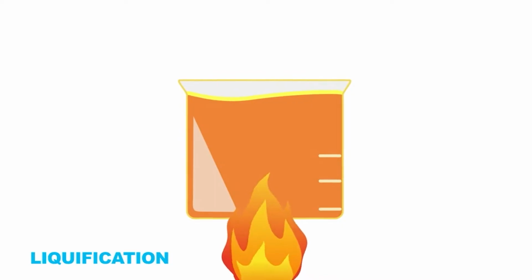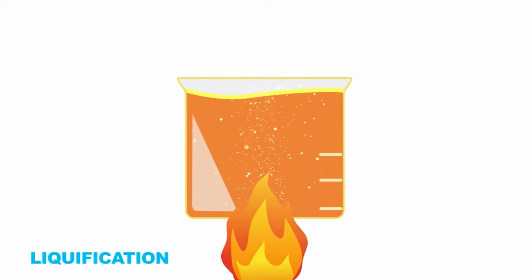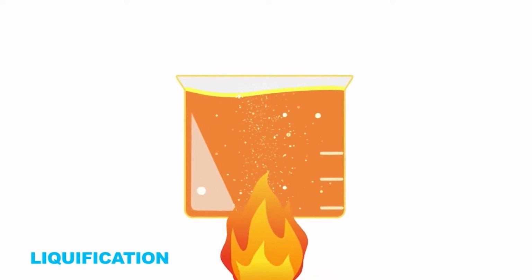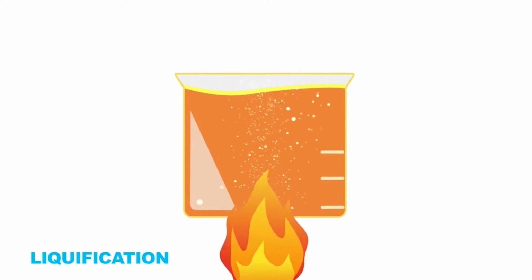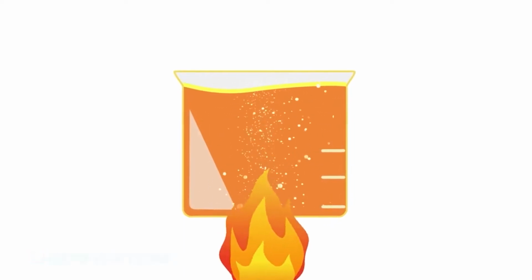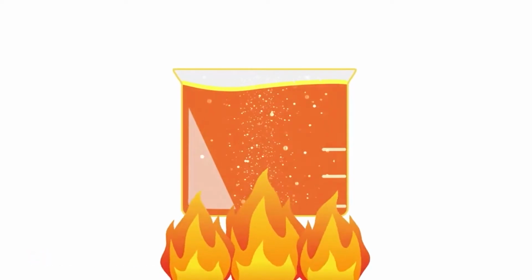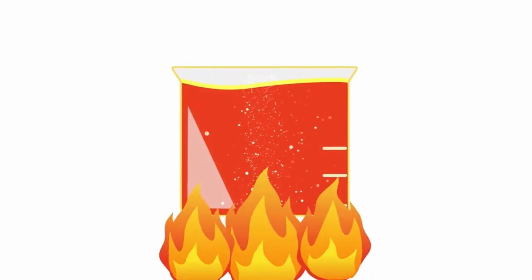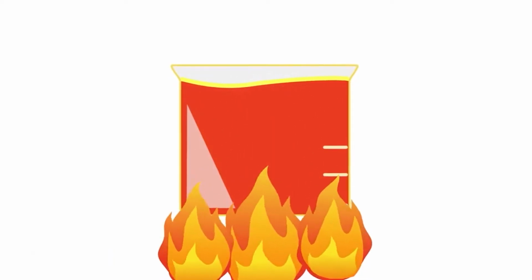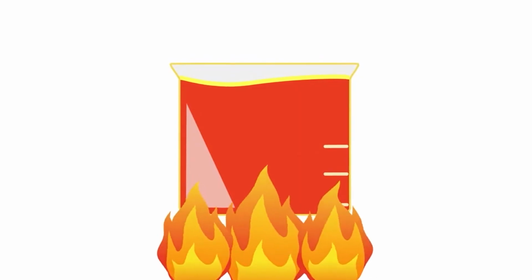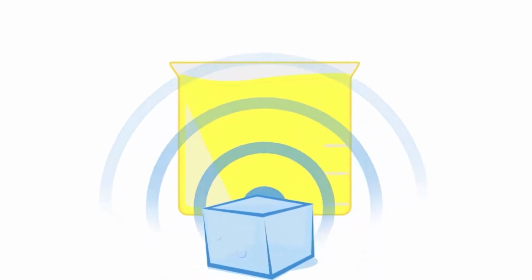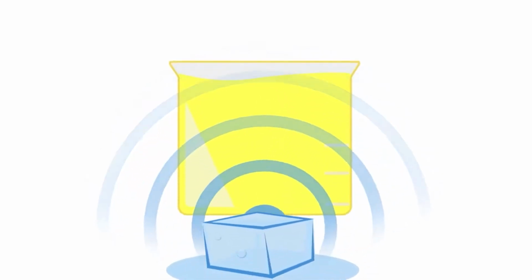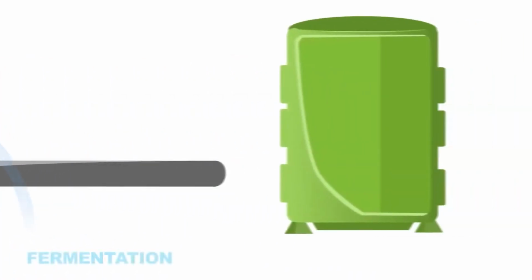The pH is adjusted and the mash is heated to a certain temperature. Enzymes are added, and at the proper pH and temperature, the cornstarch is converted into complex sugars. After this liquefaction process, more heat is added to cook the mash, which kills unwanted bacteria. The mash is then cooled to around 90 degrees and sent to fermentation vessels. Now we're ready for the next step, fermentation.